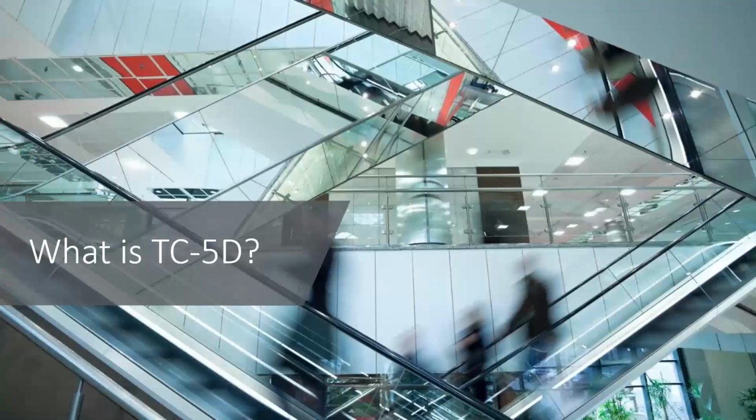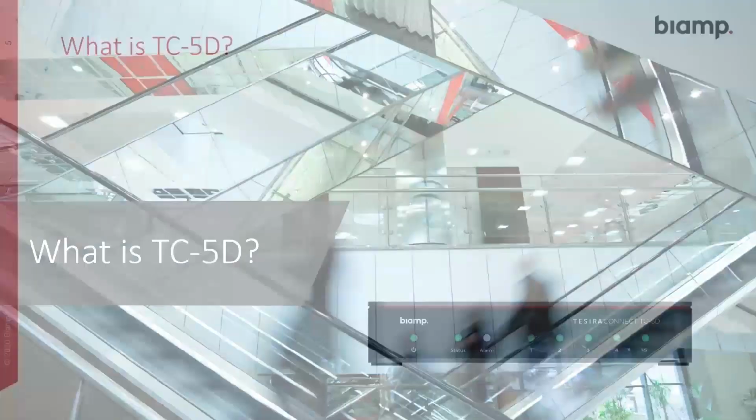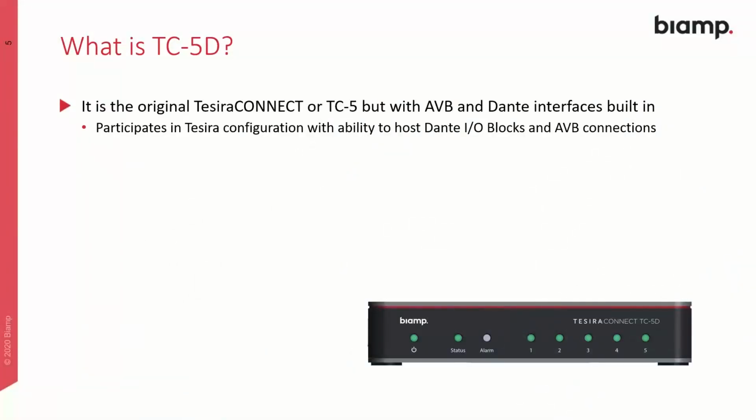So what is the TC-5D? Well, if you're familiar with the original TesiraCONNECT or TC5, it is the same, but it has AVB and Dante interfaces built in. If you're not familiar with the TesiraCONNECT or the original TC5, it is our 5-port AVB device for constructing Biamp-centric AVB systems. It has 5 ports, and 4 of those are capable of providing full PoE plus budget to your devices.